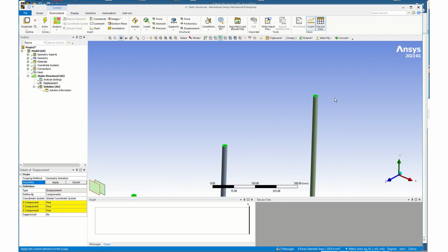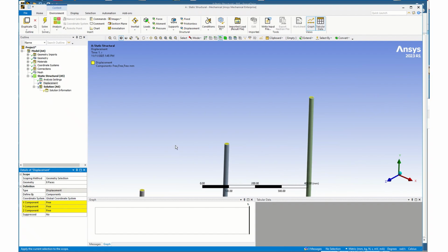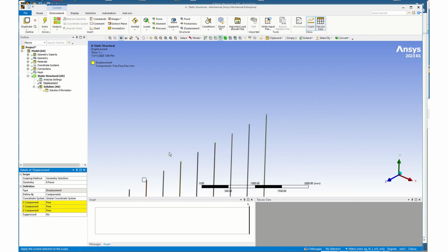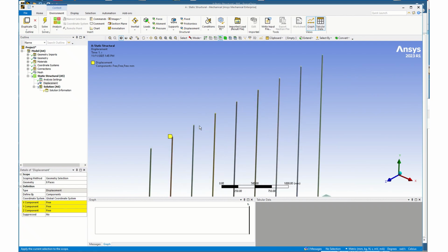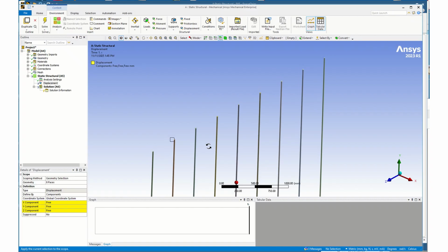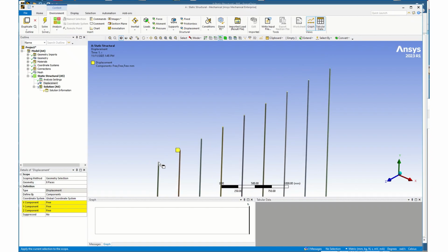To make sure you got them all, when you come over here and click apply, you should see that there are 9 faces. I only have 8, so I need to see which one I missed, and it looks like it was this very first one. So I'll rotate those, and I will pick these faces again. I'm on face select.